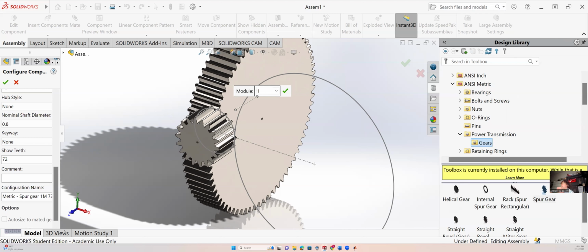So if you make one very, very small, it's going to see a lot more fatigue wear than say the bigger one. Okay. And it will wear out much, much quicker because it's distributing its lifetime load on fewer gear teeth. Okay. So normally your general rule of thumb is 4 to 1. I'm sure there's more derivation behind that, but we're not going to go into that right now.